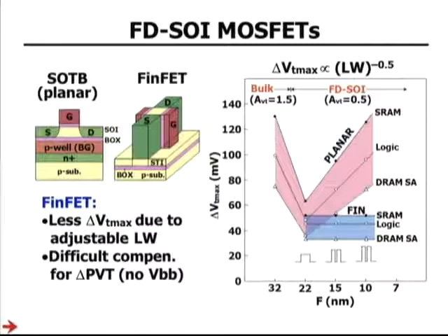To my knowledge, however, it is more difficult for FinFET to compensate for PVT variation because substrate back bias VBB is unavailable, thus calling for something new.